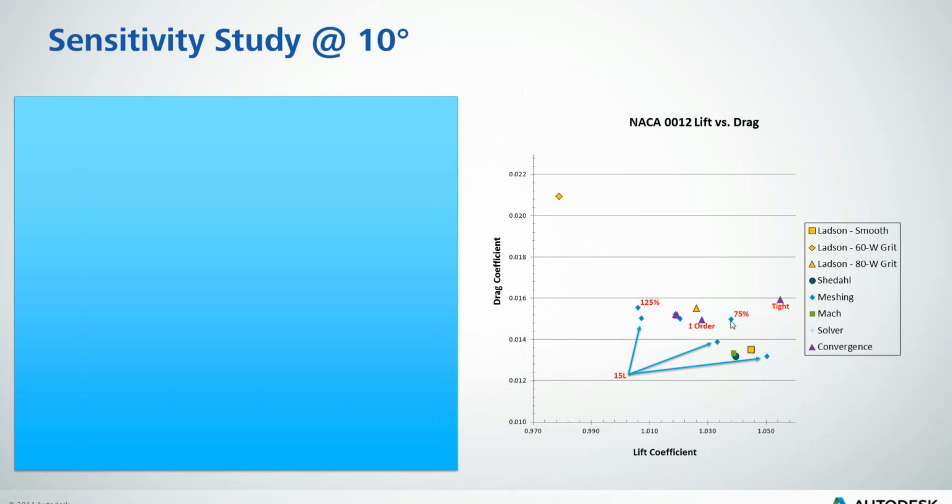So have we gone far enough? Probably. Probably with an error of all the other 40 different wind tunnel test data that we already have. Okay. From there, I just went from Mach 0.08 to Mach 0.15. This is reaching more of the limit of incompressible assumptions as the air accelerates around the airfoil. Still within reason.